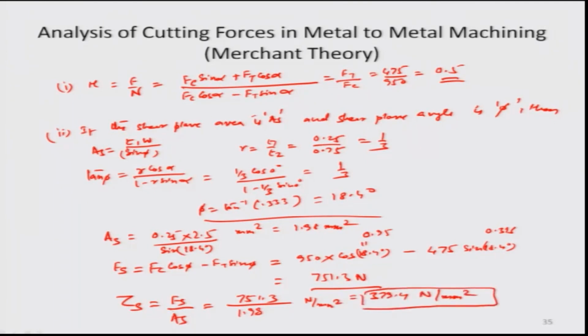So, that is how you actually tackle these problems about the different unknowns, like the ultimate shear strength in the zone of cut, by looking at the geometrical parameters and also the measured forces in the cutting and tangential direction at the zone of cut. So, with this I would like to end this topic.